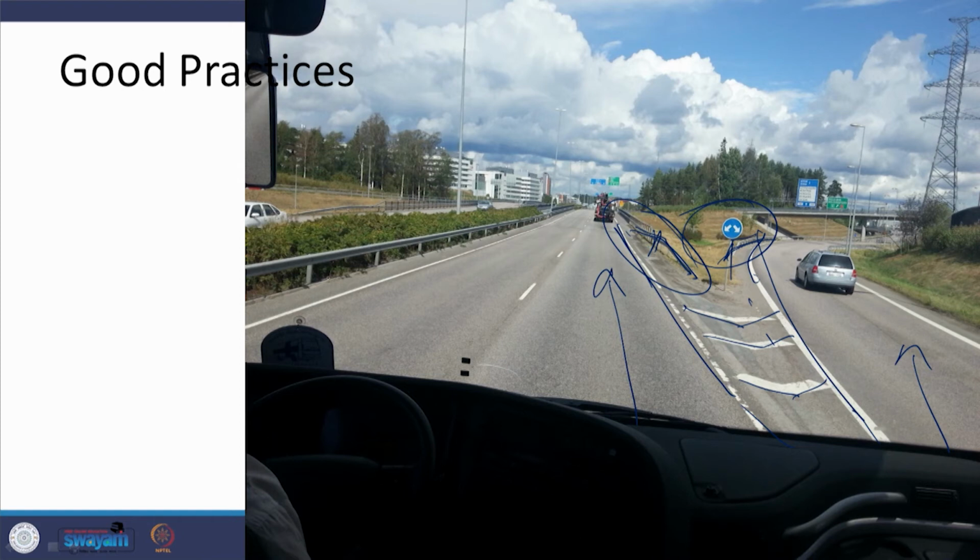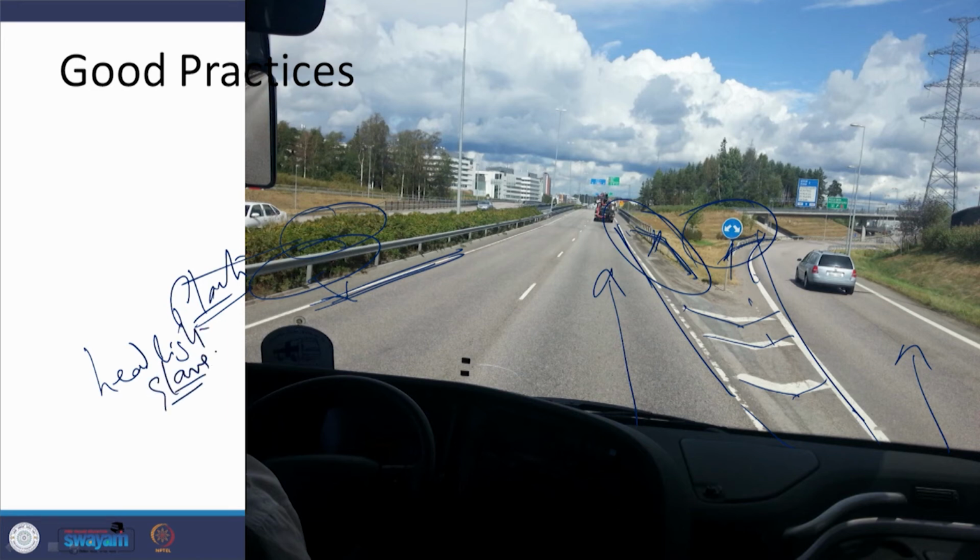On the other side, what you can see is again an edge line. At the back setback of an edge line, there is a crash barrier, and then there is a median, and on this median the plants have been planted, and therefore the headlight glare has been reduced. So, there is no issue of headlight glare when the traffic is moving in either of these directions. So, that is another good practice being followed in this case.